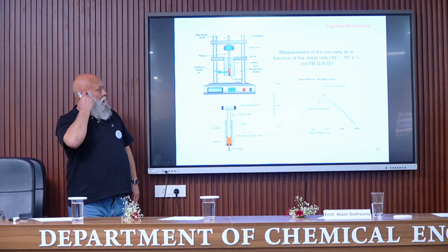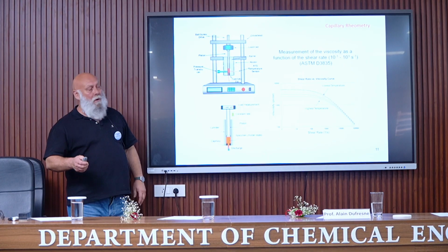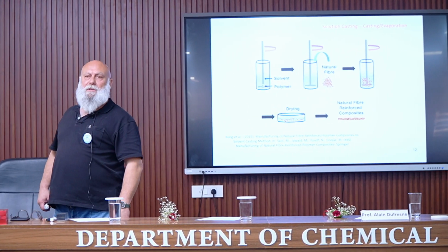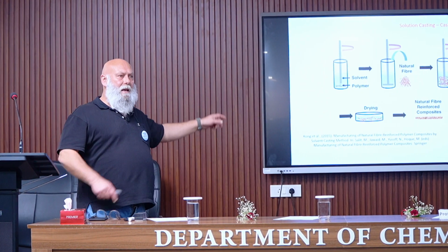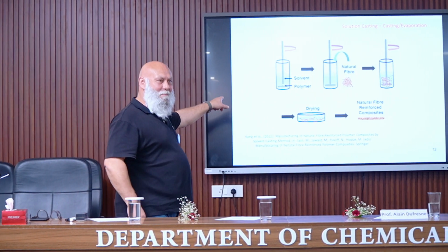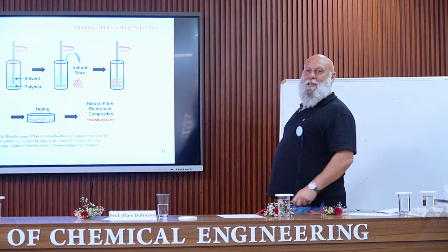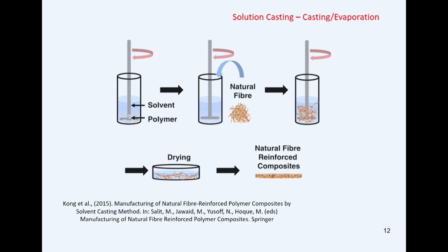So now I will come to the processing techniques. I have added this slide because it seems that this afternoon you will use this, which is solution casting or casting evaporation. So it's very easy to perform. For this, it's necessary to use a solvent. So the polymer is dissolved in a solvent. If it's a water-soluble polymer, of course, water is used.